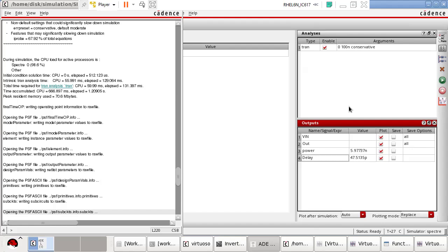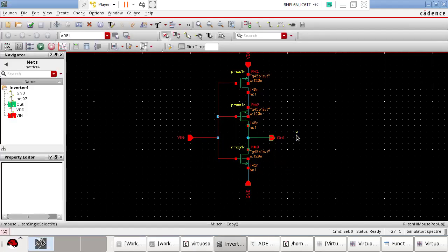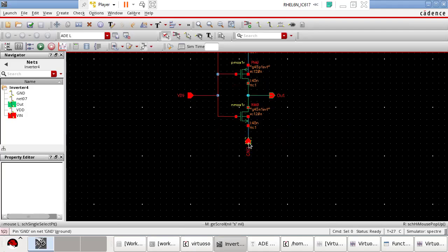So we have seen both the techniques. What we have noticed is that the size of PMOS is way higher than the NMOS. So in this case, the size of the device will increase more than the size of the device that increased in the previous case. So the device size will increase in both cases. The dynamic power dissipation will increase in both cases, and the delay will increase in both cases. Now I'll take one case where I use both sleep and stack in a circuit in a single go.